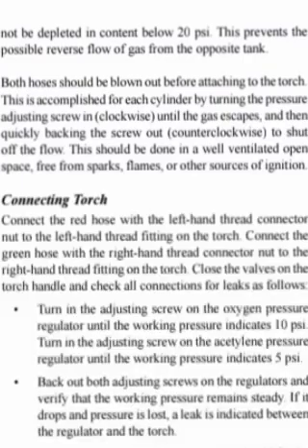As a recommended safety practice, the cylinder should not be depleted in content below 20 psi. This prevents the possible reversal of gas from the opposite tank. Both hoses should be blown out before attaching to the torch.